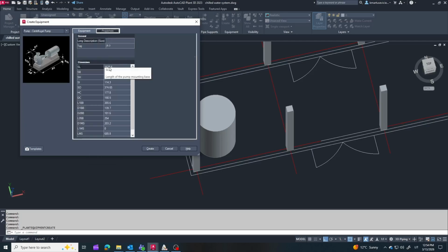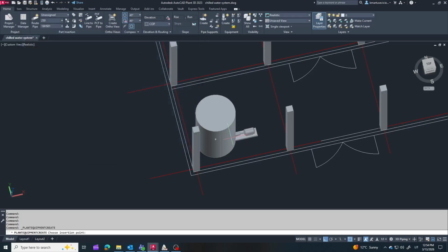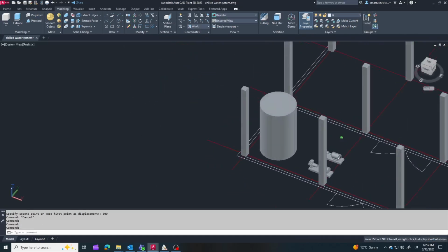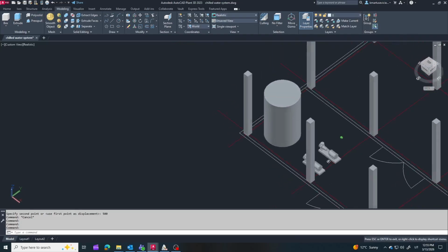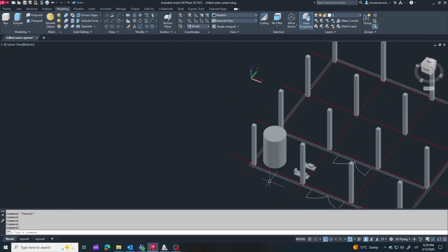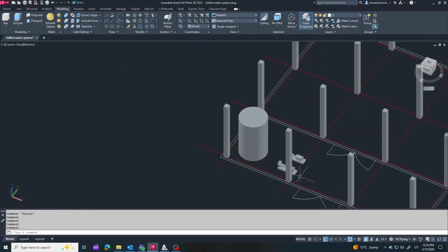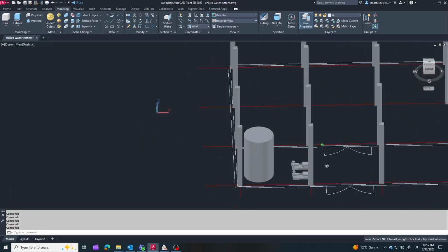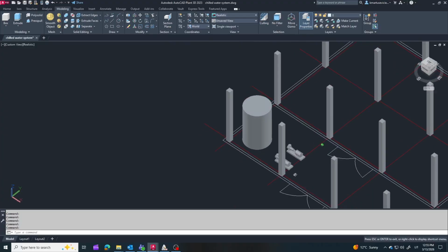Our system also needs circulation pumps. I place them in the user loop because this is the part of the system that distributes chilled water to the cooling users. On the chiller side, separate pumps are not always needed, since chillers often already have internal pumps. Because of that, in this model, I do not add extra pumps to the chiller loop.